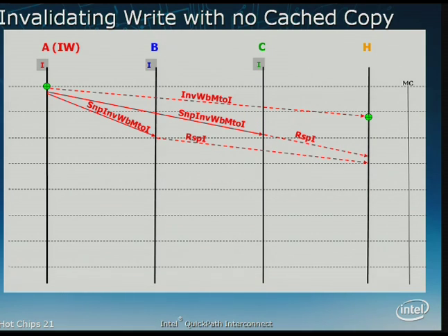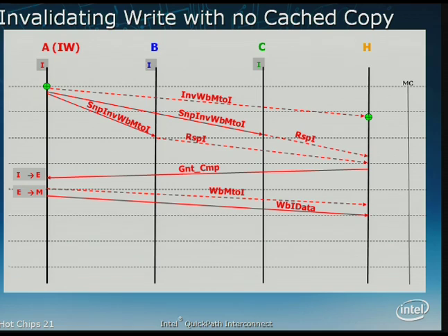In my particular case, it was a complete miss. We now give the grant, or the ordering point, to the IOH. At this moment, that transaction, whether or not it was speculative, can now be ordered. So basically, for the producer-consumer model of PCIe, that's the ordering point that it must adhere to. At some time later, data is then written back to memory.